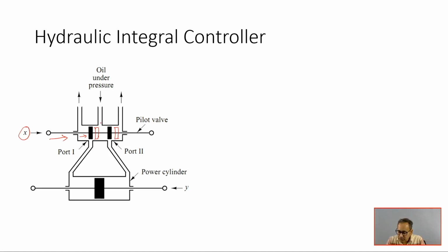Okay. So, in this position you can see this pressurized oil is allowed to flow through this path, because this port 2 is uncovered when it is shifted to the right side. So, fluid is coming in this direction and it is applying pressure to this particular power piston. This is generally connected to a higher load, but here it is considered to be negligible load. Now, fluid pressure force is applied at this side of the piston, whereas the oil at this side is connected to the drain side, because this is uncovered.